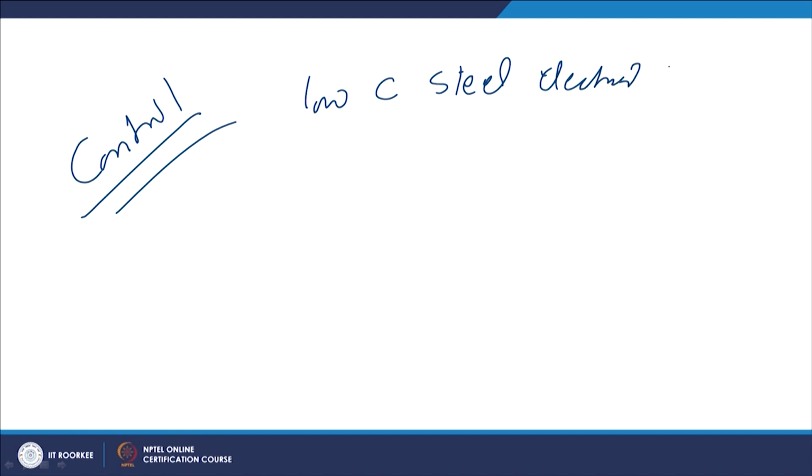So, our yield strength is less, which will be reducing the tensile residual stresses, as well as facilitating or easing out, making the weld metal more accommodative for the locked-in strains.